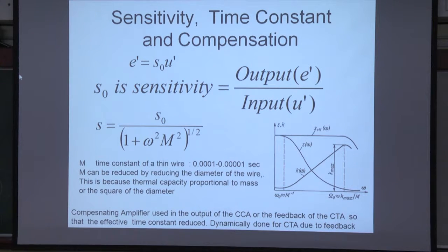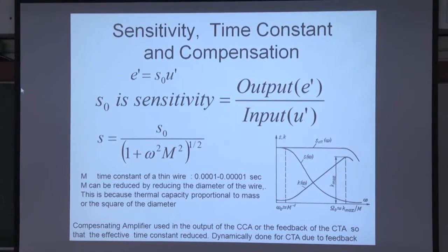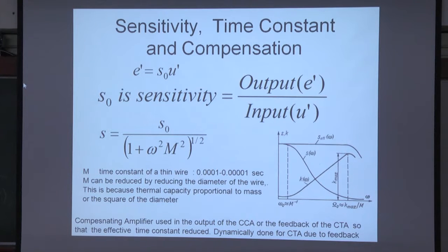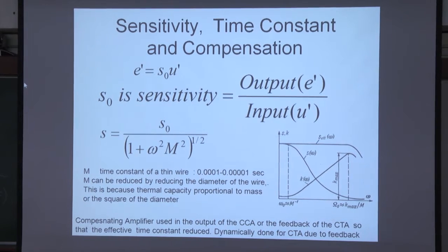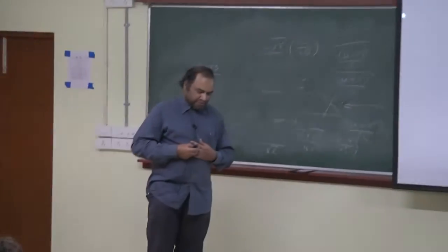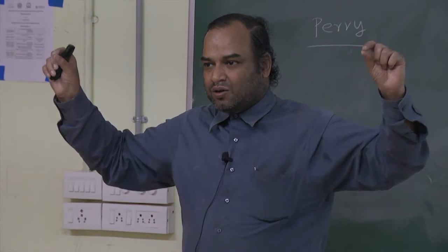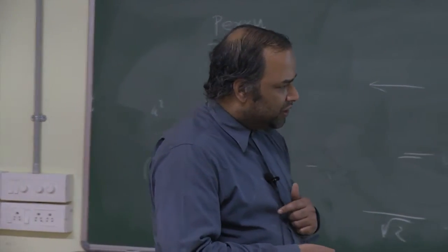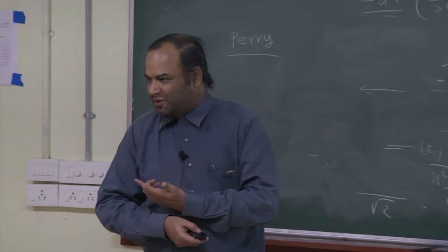you remember, people will sell you all these tungsten wires and say it's 1 micron, right? There's no guarantee it's going to be uniform, because the wire drawing technology may not necessarily be uniform, as we have seen how it is done. In fact, many years ago we went to one of those disused light bulb manufacturers, because they use tungsten there. We got them to make tungsten wires drawn out for us, almost on an experimental basis 15 years ago, and we got probably a few kilometers of the wire for about 10,000 rupees or so, whereas if you had imported, it would be a king's ransom. But the point is, there's no guarantee that the wire diameter is constant all through, especially if we make it very small. The drawing technology becomes more complicated as it becomes small. So there's a limit to what you can do. And secondly, the strength. It will break if you make it too thin. You can only make it so thin.